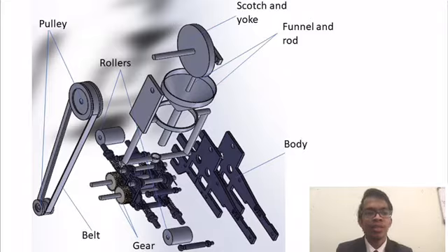Then there is the body, and there are the rollers. The rollers will move and grip in different directions and feed the anchovies to the blade. The roller is connected with the shaft and a combination of two gears of the same dimension and design. One shaft of the roller will also be connected with the driving pulley, and there is the motor connected on the shaft.